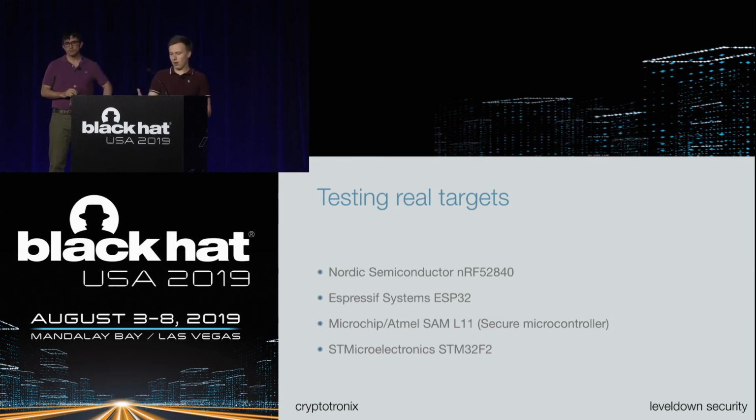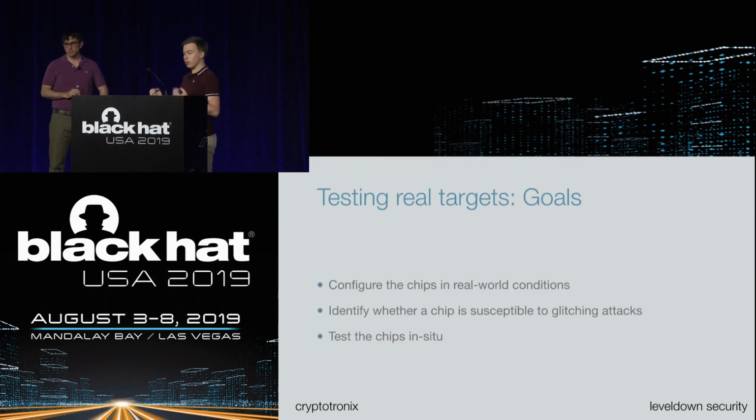Our goals for this were to configure the chips in real-world conditions and just identify whether a chip is susceptible to glitching attacks. So the idea is not necessarily to have a full exploit for all chips, but just to give a very simple way of checking whether the chip you are going to use in your product is susceptible to glitching or not. And we also want to be able to test the chips in situ. So for example, we just order a basic development board, solder off some capacitors, and then we go ahead and glitch it without having to design a custom board, without having to solder a lot of stuff. All you need is a hot air gun and a soldering iron, and that's it.